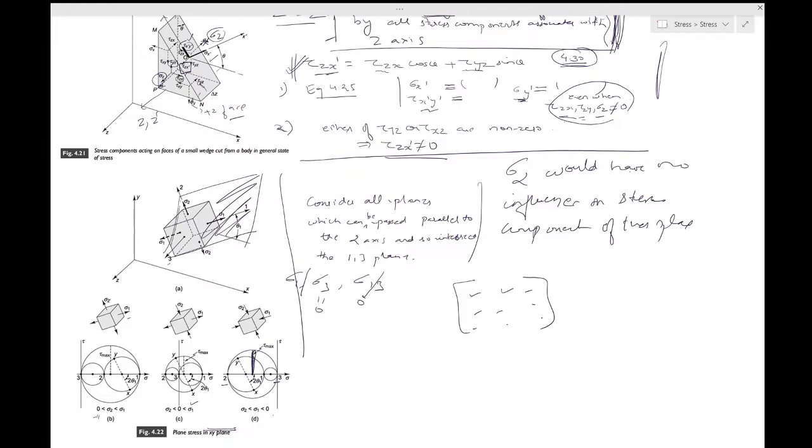The plane of stress in this case is this, but you have a 45 degree inclination. So this plane which you see is 45 degrees inclined, and that is why it shows a 90-degree inclination in your Mohr circle. This is the last observation for a truly three-dimensional case.